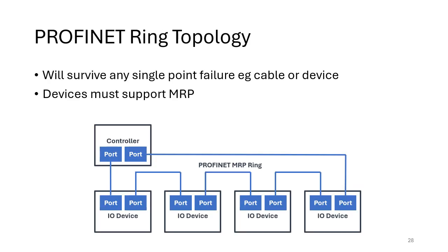So what if you're worried about one of those cables being broken? This is probably the thing that goes wrong most on sites. Cables break. They might be under heavy stress loads. Someone might damage the trunking they're in. Forklift trucks drive into them. You get physical damage. So those cables are probably the least reliable part in a distributed system.